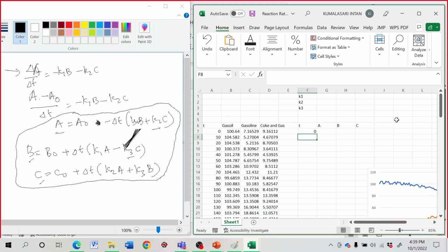And then we will start, well, in this case you could start with 10 or whatnot, but we'll start with 1, because this Euler calculation is very sensitive to the delta T. If you have too big a delta T, the calculations will be wrong or inaccurate. But if you have a very small delta T, you will need much more memory and much more computing power. In this case, because it's very simple, we will use 1. But this is something that you have to do trial and error on. Since I made the case, I know.